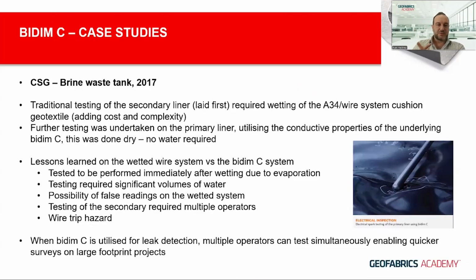So what that showed was that the traditional testing was undertaken on that secondary liner first by wetting the textile, as I mentioned, but that added cost and complexity because you have to bring water and spray and prevent any evaporation so that the survey can be enabled.